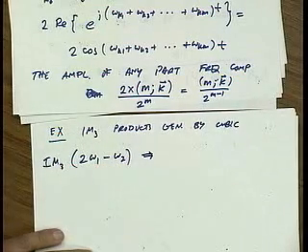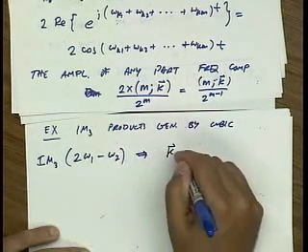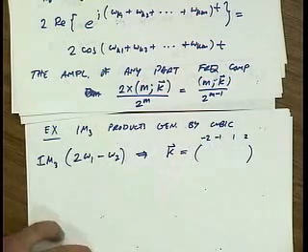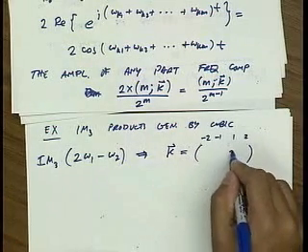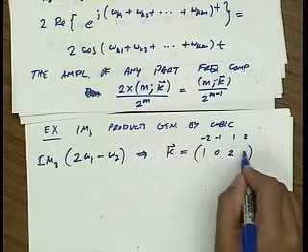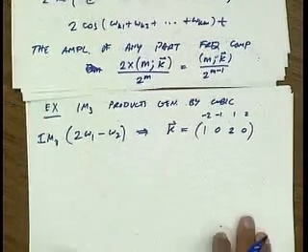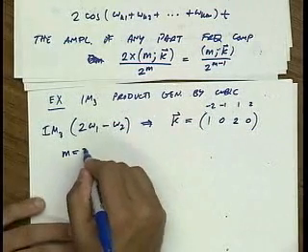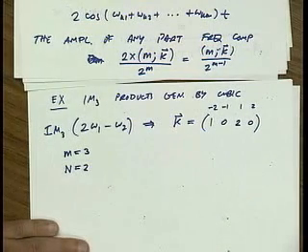Well, first thing we do is we write down the k-vector for this particular IM3 product, and I write down my columns here, which tell me which frequencies I'm interested in. And we did this already. This has 2 frequency omega 1 and 1 frequency minus omega 2. So this is my k-vector. Okay. Everybody see where that came from? Yeah, good. Now m is equal to 3 and n is equal to 2 for a two-tone test, right? I should have said that first.